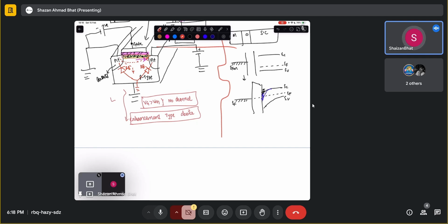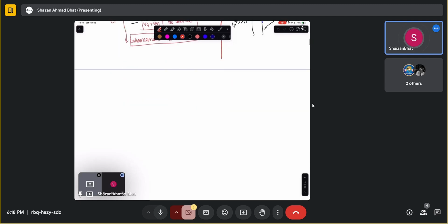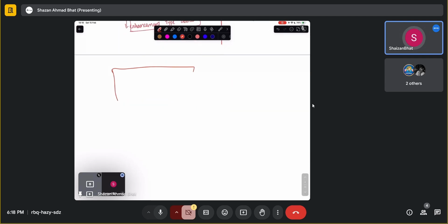There are different considerations you might have studied. From the MOSFET, if you have N plus regions, this is oxide and this is gate. You know that there is a depletion charge present here. It will be slightly towards the N plus region because it's heavily doped, and it will be mostly penetrating towards the P substrate, which is this.